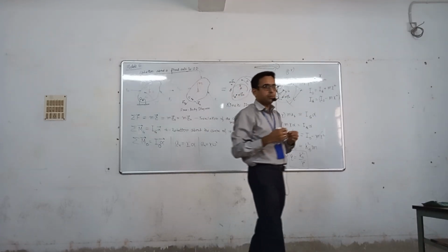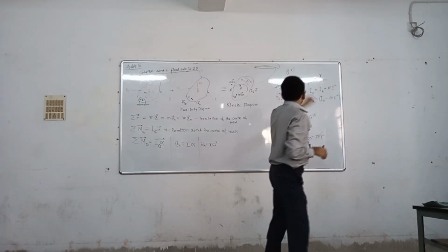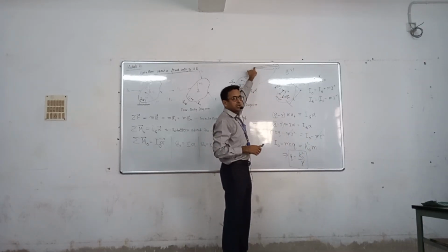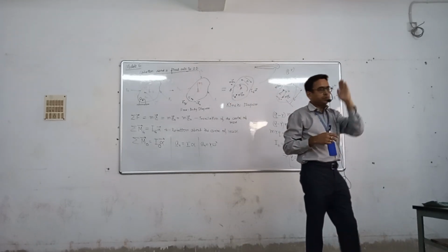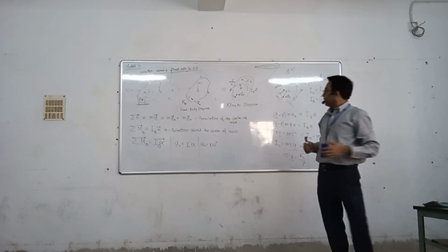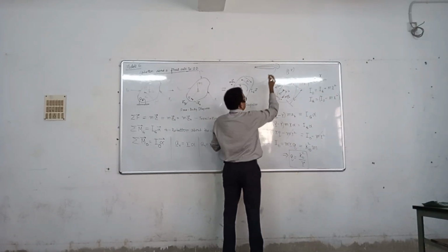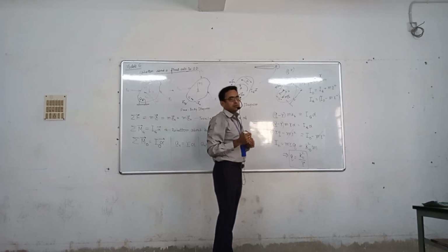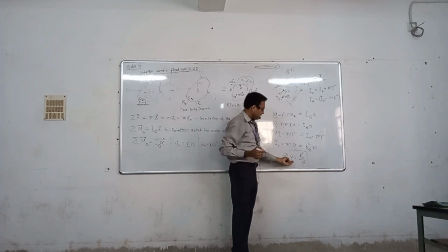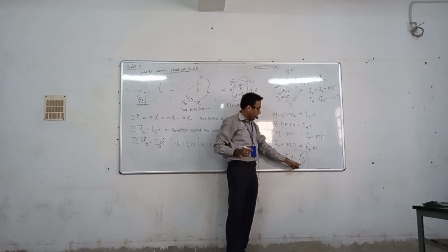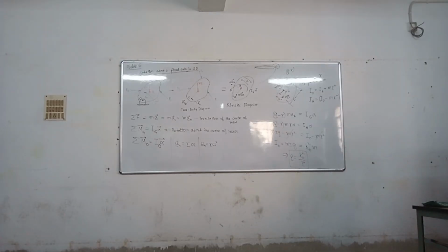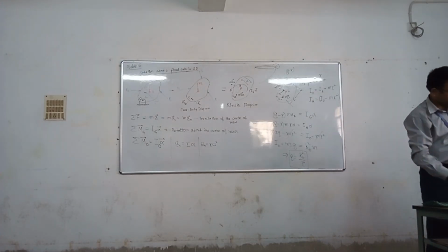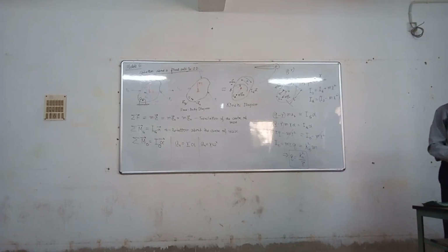Now once it breaks the metal, there should not be any tangential load on the bearing. If there is a tangential load on the bearing, then it may break after a certain number of uses. So this strike will be done at the center of percussion. If K0 square is known and R is known, then Q will be known. So it is fixed for that particular system, for example a baseball bat. Okay, thank you. If you have any question, you can ask.